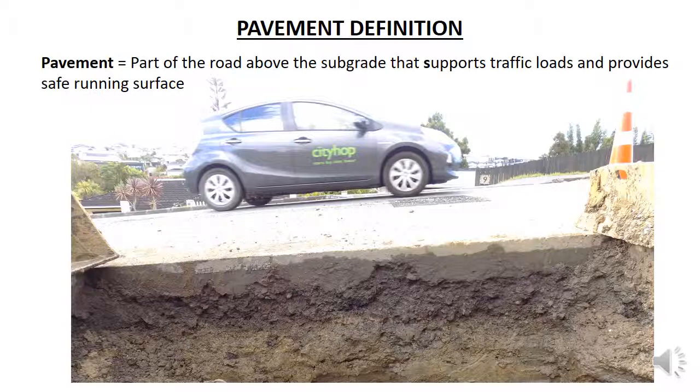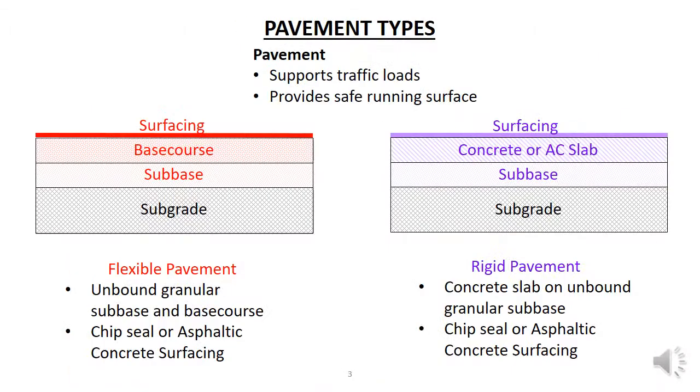This photo shows a section through a flexible pavement. You can see that there have been several surfacing layers applied over the years. The top surface is presently asphaltic concrete. You can see a 150mm thick base course layer beneath the surfacing. Beneath that is a clay subgrade.